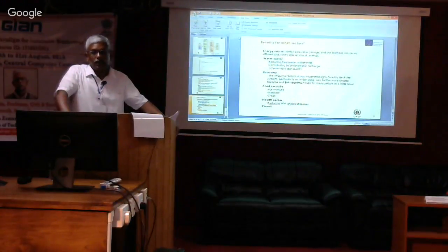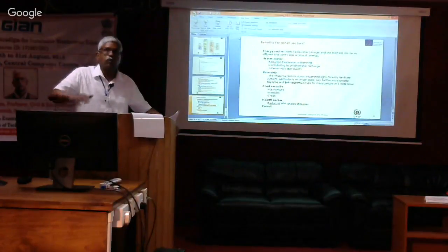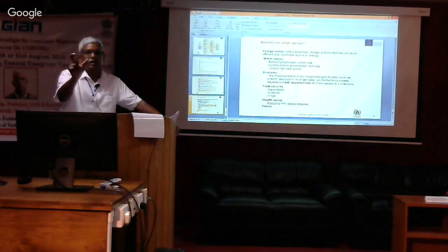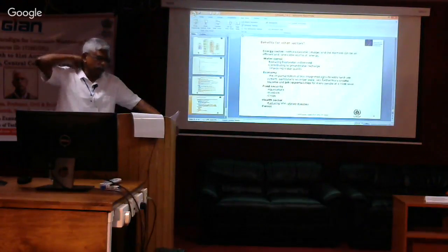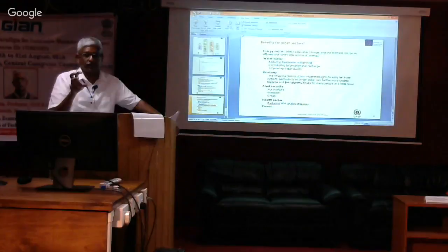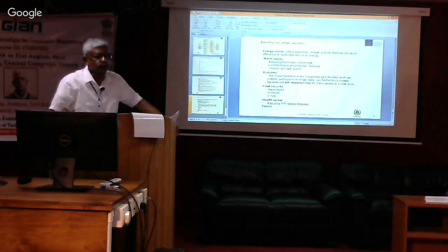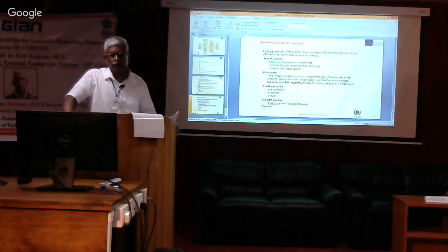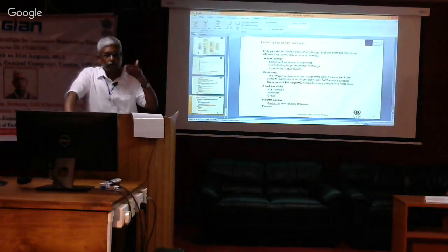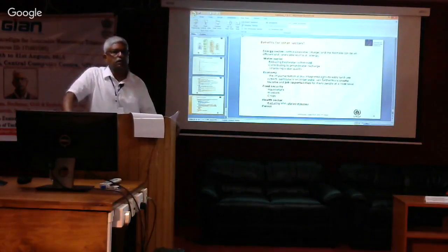And now we have been able to go one step further. So start with the septic tank, then rather than a soil absorption system, which is what we call a passive technology, you can have active technologies, even at the scale of a residence, whereby, and I won't have the time to get into it, but I can share with you some of the technologies that we have done, where you use principles of biotechnology to not only remove nitrogen and phosphorus, but also more.